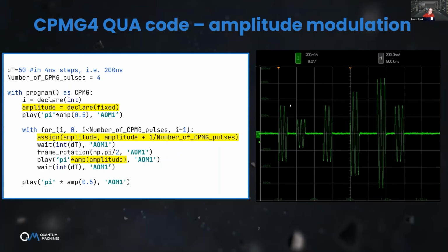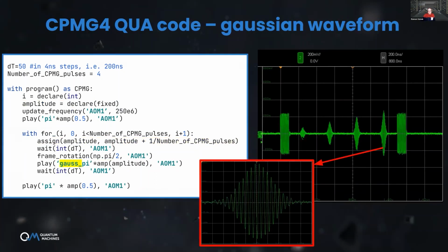So you see, I didn't need to store a different waveform, a different parameter for each and every signal. So here it's a constant waveform. It's not very maybe impressive, but you can do this with a Gaussian as well. You can change the amplitude, and it will come out phase coherent just like before. If I would superimpose here another Gaussian from a different channel, they will match. They will be perfectly phase coherent or not, as I wish.